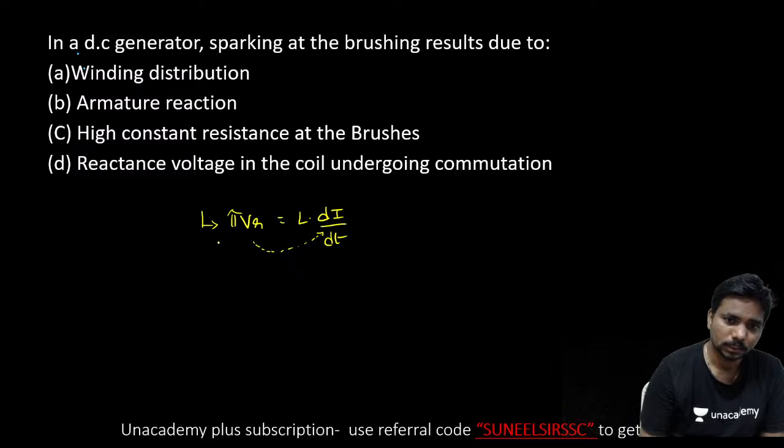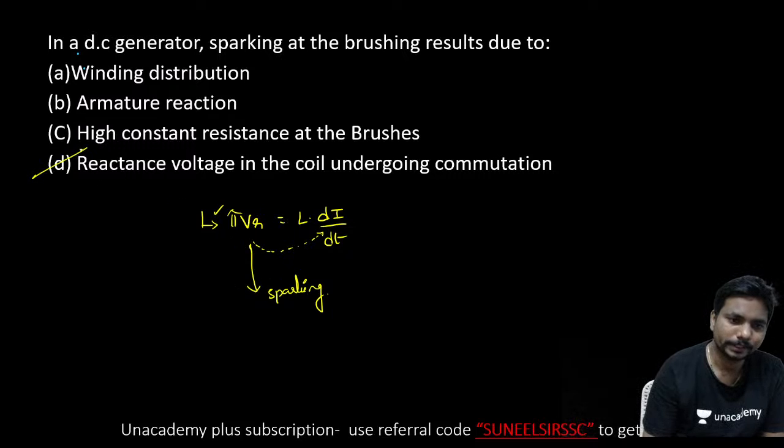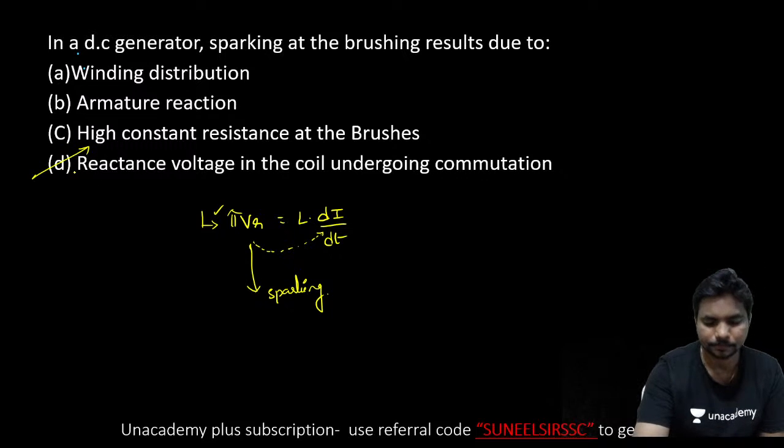So in that case we are getting sparking due to reactance voltage. If you reduce the reactance voltage, you can reduce the sparking. So the answer is option D.